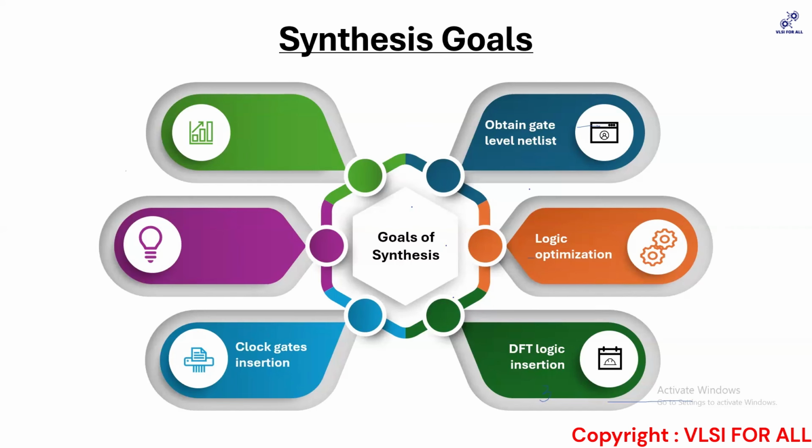See, I stated, right? It can happen that, for example, the PNR folks work at a very high level. It can happen, for example, that there is a change in the port placement. Let's say there were some changes in the port placement and this information directly came to the PNR folks. Now they change the port placement, so they have to change their logic placement, right? Some logic would move near to that port. Now when you're moving this logic, whatever scan chain flops were there, you have moved. So again, you can reorder it, right?